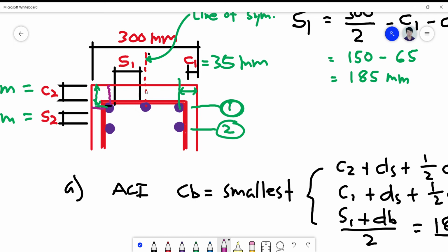Okay, also in the intermediate, you have one particular point of crossing the area of a stirrup. Okay, that's why your area of transverse reinforcement is equal to the area of the stirrup.